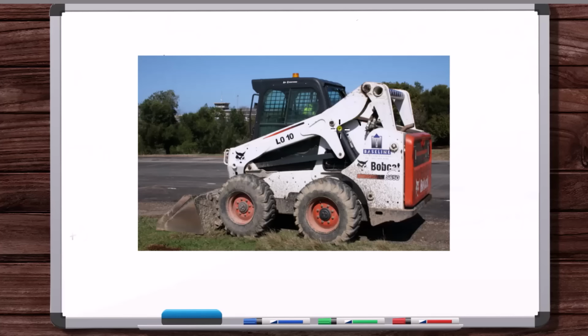So in other words, this component could be some strong rubber piece. You lift up the load and it starts off looking like this, and then all of a sudden it twists a bit. It doesn't break, but this beam twists here and this kind of caves in. In that deformed position, let's say it's not moving, we could take a snapshot. We could take a picture of that and bring that deformed shape into empty space and do all the same analysis we do in statics or dynamics if it was accelerating.